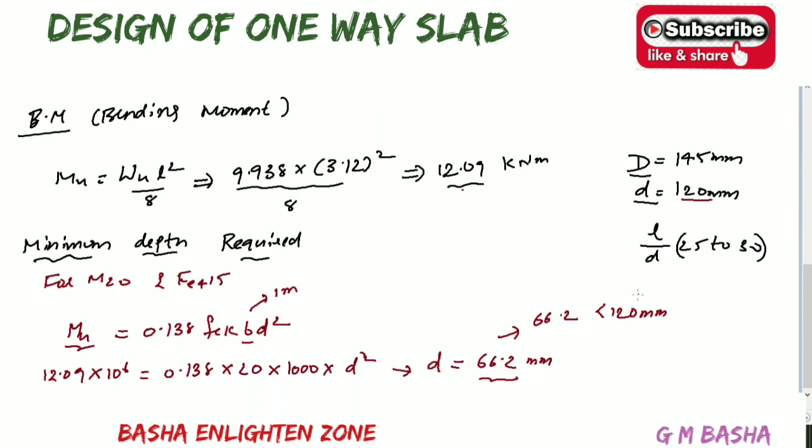In some cases, for example, if we provided some 60 mm, the minimum requirement is 66.2, which means we have to limit the value to this. Why? Because if we provide less than 66.2, it will give cracks or deflection, and the concept will be wrong. So if you assumed 60, in the trial section you can limit this value to 66.2, and based on that provide clear cover and the diameter of the bar. Then the overall depth will be something like 180 mm.